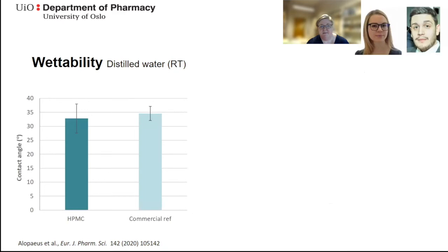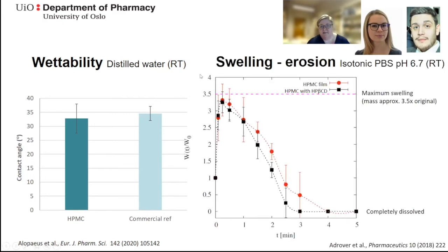They are easily wettable. The contact angles are around 30, 35, and all below 90 degrees are wettable, but the lower is more wettable, and this correlates well with moisture absorption. Then we also looked at swelling and erosion, and since these are hydrophilic polymers, they will swell up